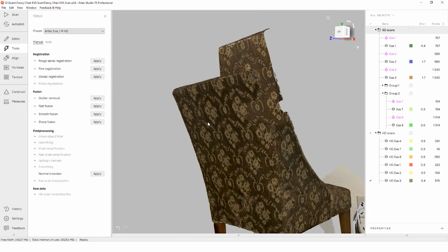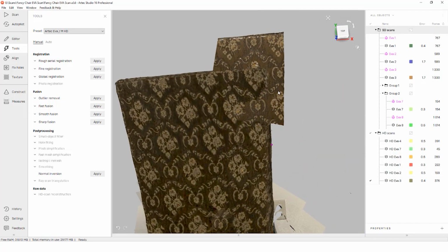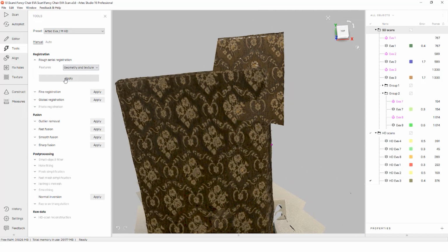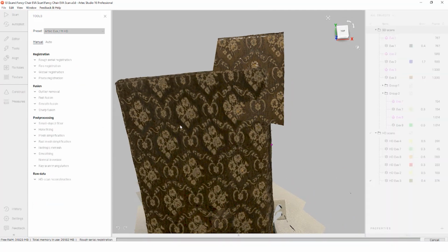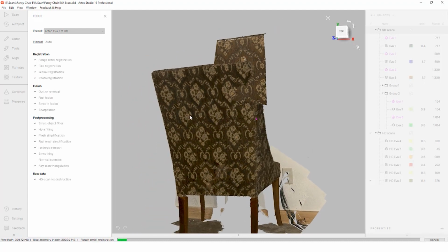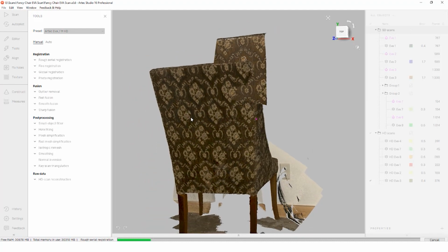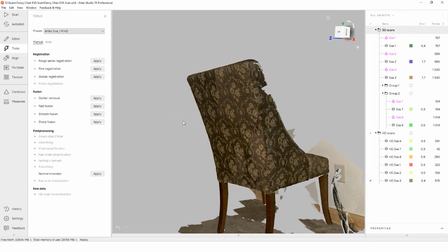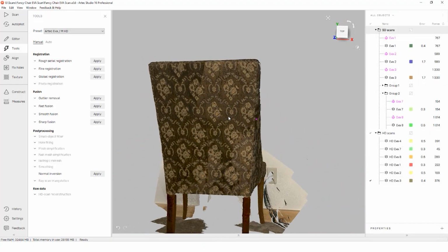We can see that one of our scans looks to have a slipped frame. This is caused by the scanner losing tracking for a moment and aligning to an improper frame. Since this is a small portion of the scan, we can likely fix it by running a registration on the scan itself or manually deleting the frames that made this section. Having background information such as the wall or ground can help with correcting these during that registration process.